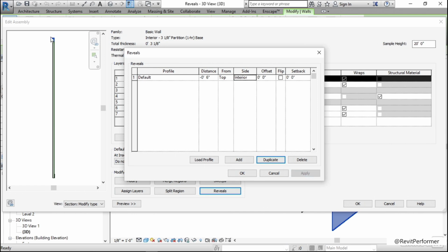Right now we can see in blue over here underneath the preview that that's the profile shape. Well, right now it's really just removing the entire top of the wall, and I don't want that. So let's choose an offset value to move this shape over toward the right. I'm going to choose a negative number like -2 inches and just see what it does. Click on Apply. See how it's now moved it over? But really, it hasn't moved that shape over quite enough for it to not go over the entire top of the wall.